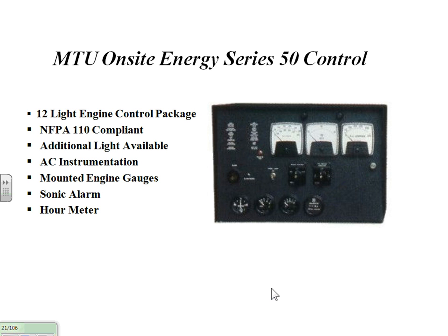A lot of these sets have to meet the NFPA 110 standards. So the control will alarm if there's a problem that it sees, like high water temperature. For whatever reason, the temperature on the engine is going up. Oil pressure is dropping. Maybe we got a leak someplace. That's what the NFPA controls are all about.